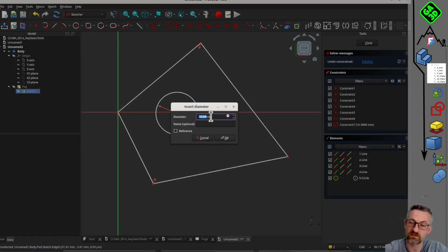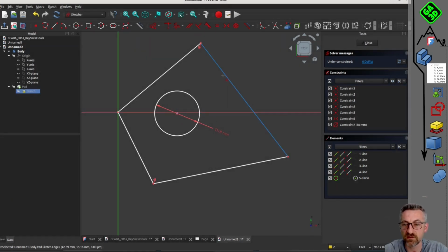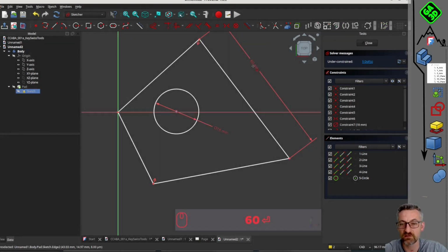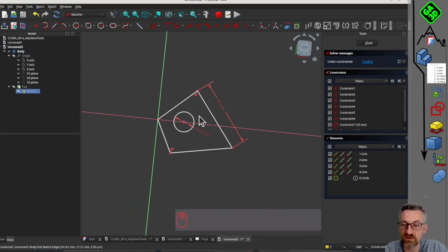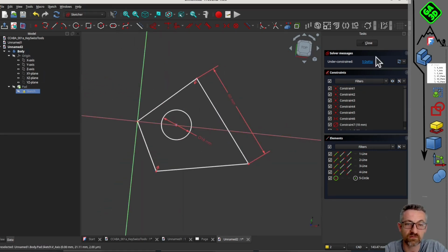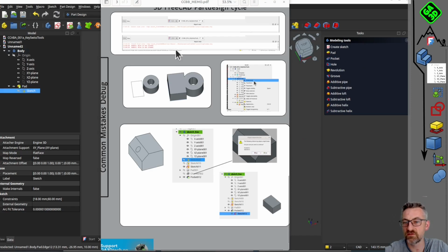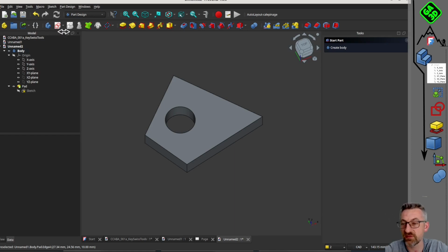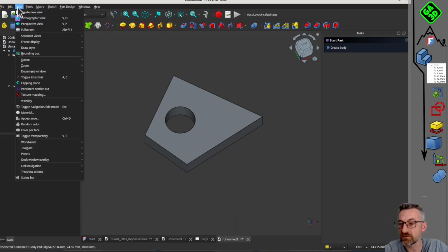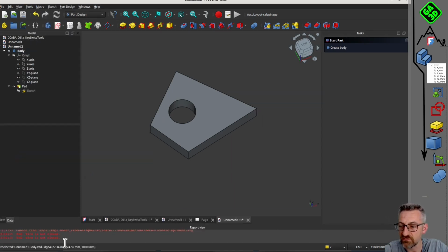If we reactivate our 3D view, we see our volume there. Then we want to geometrically define some things. So you select the elements that interest you, in this case, the circle. Here you can either say you want a diameter, etc. But now in FreeCAD, it makes your life easier. It automatically detects that it's a diameter. And you can define the diameter there, or this length of 60 millimeters. There you go, that's really, in 2 minutes, the basics of the sketch workshop in FreeCAD. But I think it's good to talk about it.